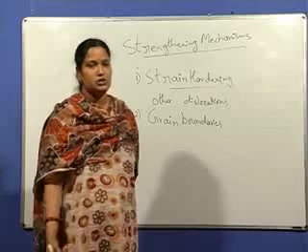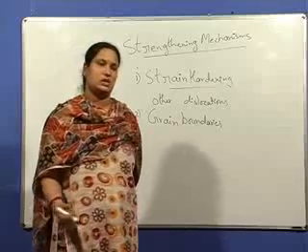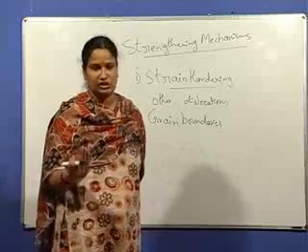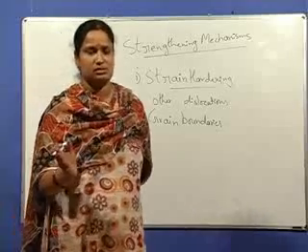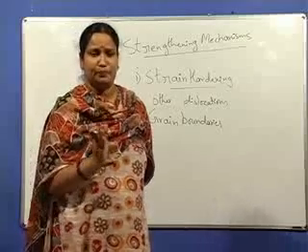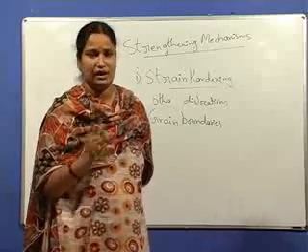So grain boundaries are also obstacles to the dislocation motion, because for the dislocation to move into the adjacent grain, it cannot move directly across the grain boundary, because the slip has to change its direction.